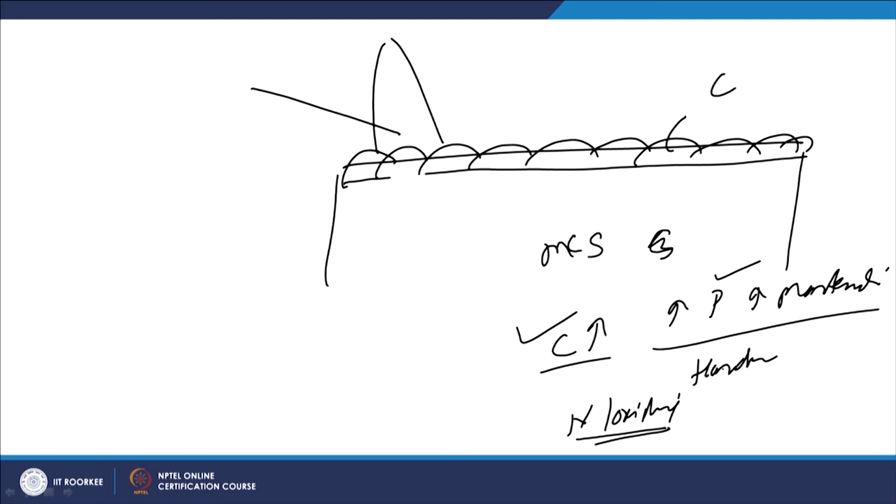So, carburizing flame leads to the enrichment of the carbon content, which will be increasing the fraction of the pearlite, because increasing carbon content will be increasing the pearlite under the low cooling rate conditions, and if the cooling rate is high enough to form the martensite transformation, then it will be leading to the formation of somewhat higher carbon martensite. So, this is one of the implications related with the use of carburizing flame.